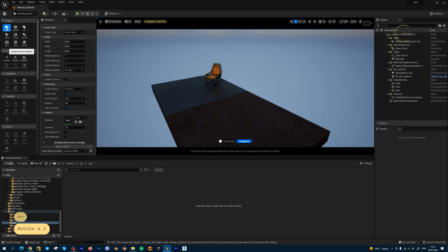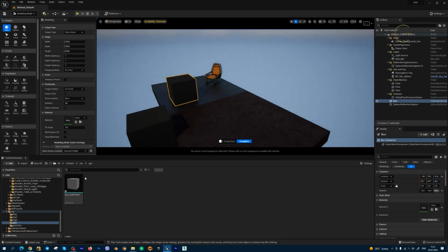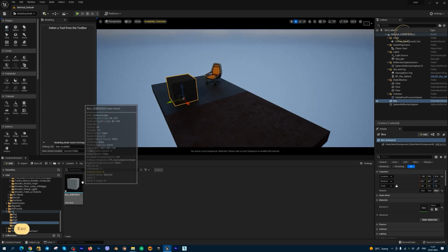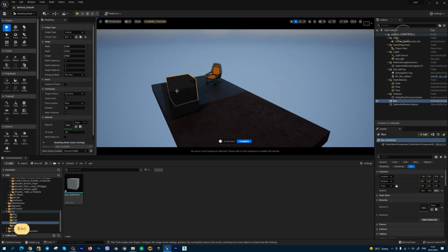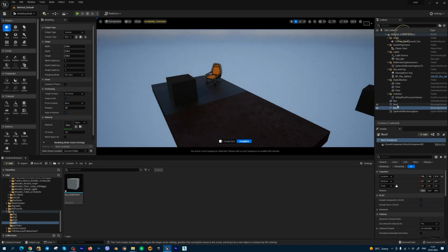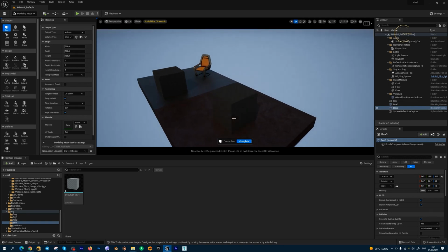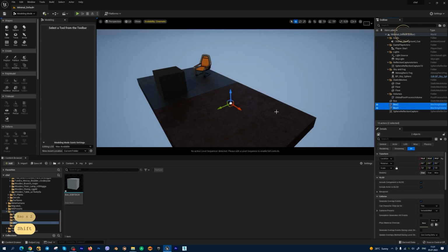What is this? When I create, for example, new shapes, for example a box, I have three types of geometry inside Unreal Engine: static meshes, volumes, and dynamic meshes. We activated that a few seconds ago. When I create static meshes, my new asset is created inside my content browser in my folder. Next type is volume. We can create volume geometry. The new box is selected and there is no geometry in the viewer. This is volumes. We don't need this in my cases.